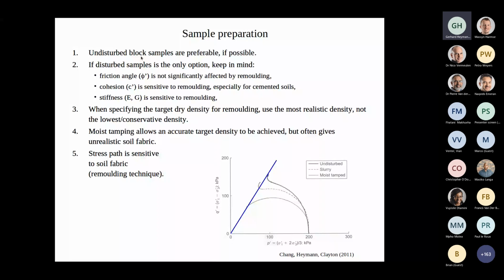If it's a loose sand, you can't take an undisturbed sample. Loose gravel, you can't. Most tailings, you can't, unless it's really near the surface. So in many cases, we can't take block samples. But if you can, do take block samples. They are definitely a preferred option.